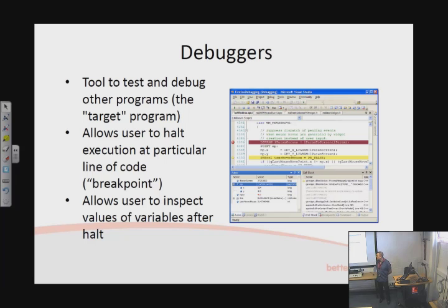And generally there'll be a piece of test equipment out there that intercepts that signal, and then that can go in and inspect the state of the device's memory and decode it using what's called a debug table, which gives you the definition of all the different variables and where they are inside the device, and allows us to actually look into the brain and understand the thoughts of that machine.